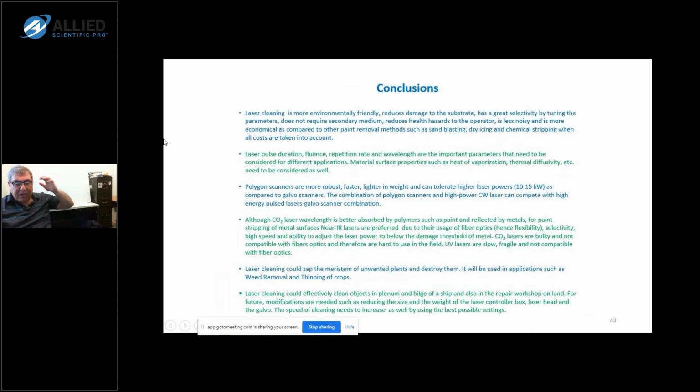So in conclusion, what did we learn from this webinar? That laser cleaning is environmentally friendly, it reduces damage to the substrate, has a great selectivity by tuning parameters, does not require secondary medium, reduces health hazards to the operator, is less noisy, and is more economical as compared to other paint removal methods, such as sandblasting, dry icing, and chemical stripping, when all costs are taken into account.